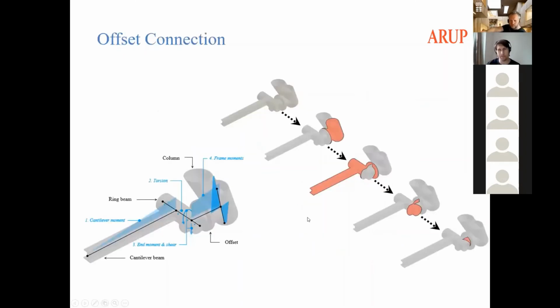Next up, we have my personal favorite of the project. It's also one of the most complex elements of the project, I would say, and it's a good way to start looking a bit more into detail at the various elements. If we look at this 3D visualization, we have the diagrid columns, which have an outer diameter of 457 millimeters. These have a splice welded to them, which is also 457 millimeters, and this is part of the offset connection. On the other side, we have another splice, which is only 355 millimeters, because the ramp ring on the other side is 350 millimeters in outer diameter. And this is then bolted together.